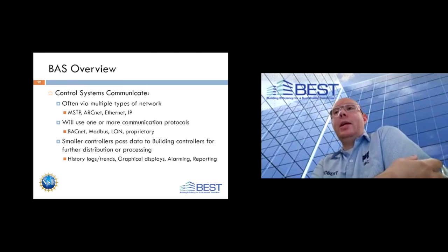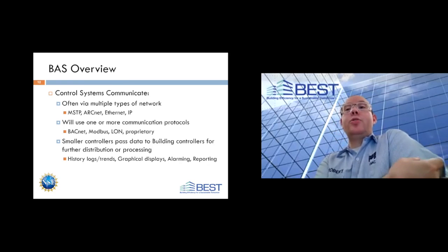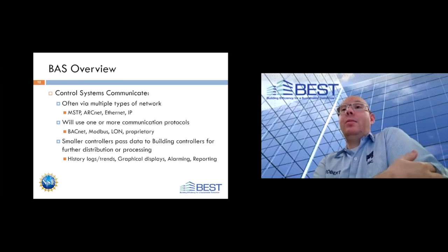And one of the last things, and arguably one of the most important things that a building automation system typically does, is record what is happening with the system, referred to as histories or logs or trends. Amazingly useful to see and visualize long-term problems, or trying to find the root cause of an issue or the start of an issue.